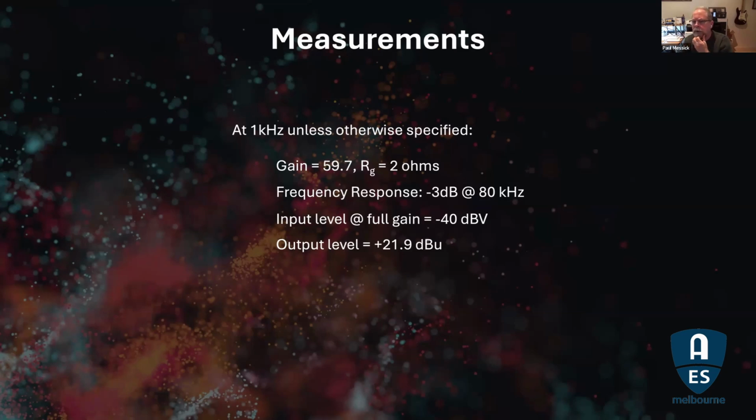And so some bright spark came up with the idea of dBu, and the U means it's unterminated, I think is what it means. It sort of means unknown. It's the same number as you would get if you were measuring in dBm. And so the conversion between dBV and dBu is the 0.775 that Rodney refers to, which is slightly over 2 dB, 2.2 dB.